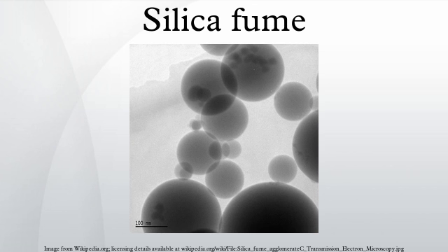Production: silica fume is a byproduct in the carbothermic reduction of high-purity quartz with carbonaceous materials like coal, coke, wood chips, in electric arc furnaces in the production of silicon and ferrosilicon alloys. Applications: concrete. Because of its extreme fineness and high silica content, silica fume is a very effective pozzolanic material. Standard specifications for silica fume used in cementitious mixtures are ASTM C1240, EN